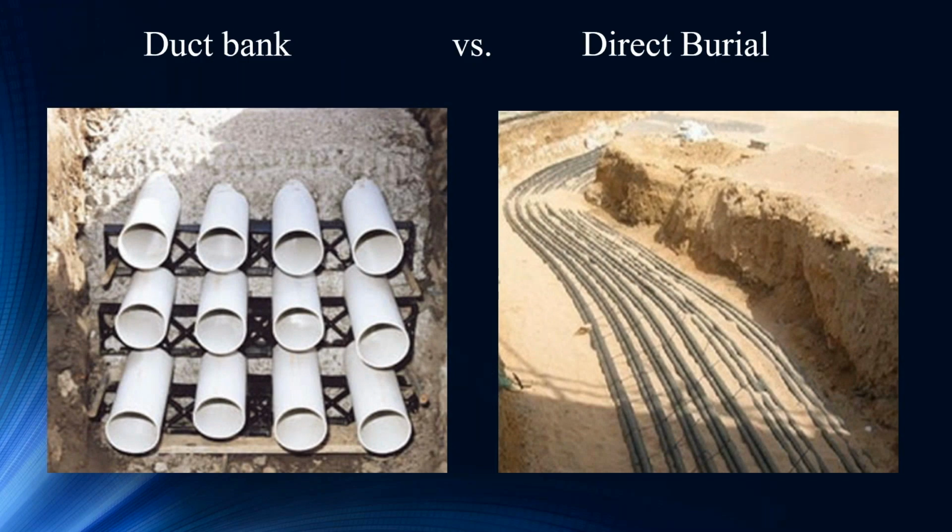Now, following the selection of the cable for an underground power distribution project, one must decide between the two major methods of laying the underground cables, namely either directly burying it or using a duct bank raceway. For direct buried raceway, basically, a trench of specified depth is dug, then a bed of fine sand is used to prevent moisture from reaching the cables. After that, the power lines are run directly over this bed of sand, and you know the rest.